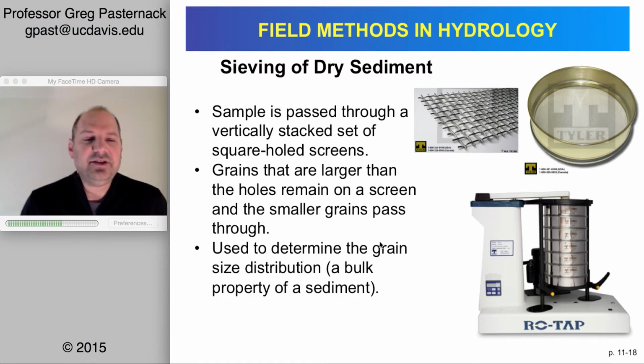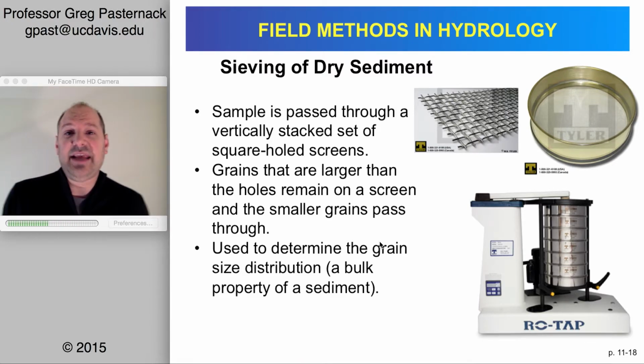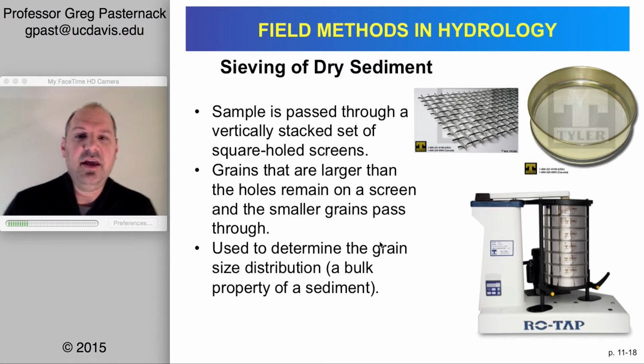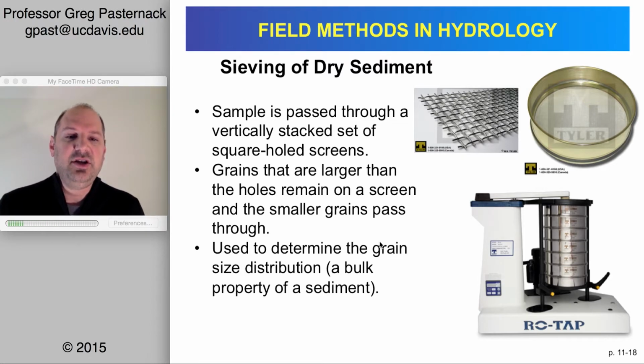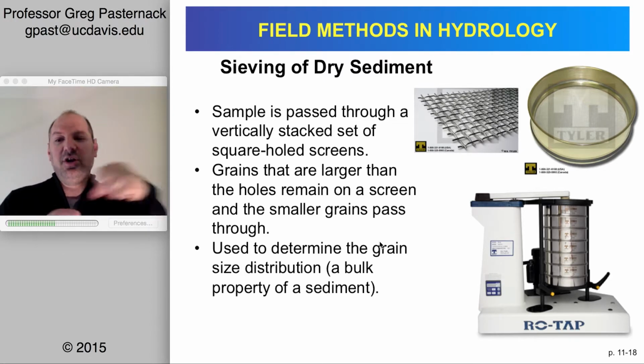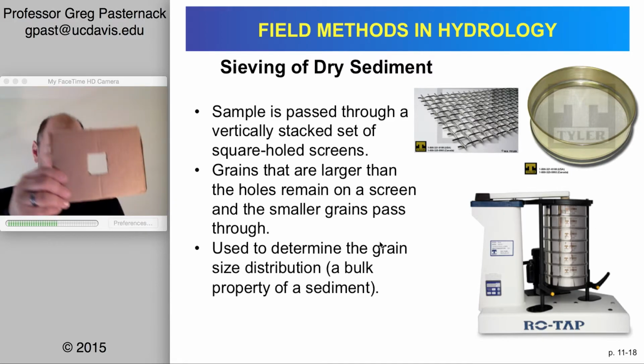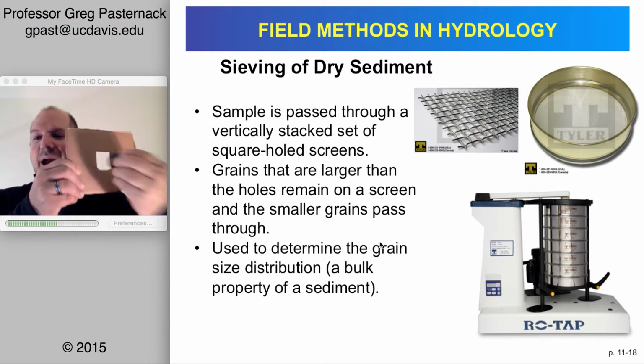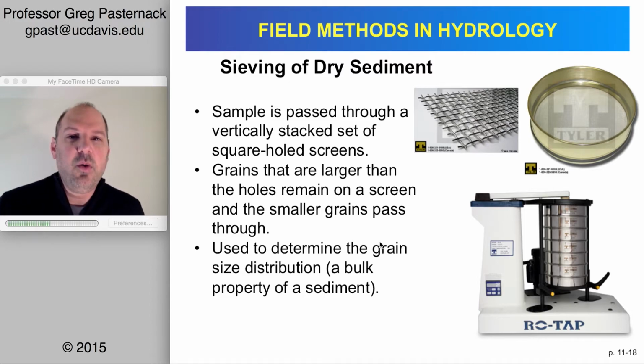The last thing I want to mention is just what do you do with sand and silt especially. You have the opportunity to dry sieve it. So instead of taking an individual grain in a gravel template and one at a time pushing through 100 grains, well, what do you do when you have 10,000 grains, right? And they're tiny little specks.